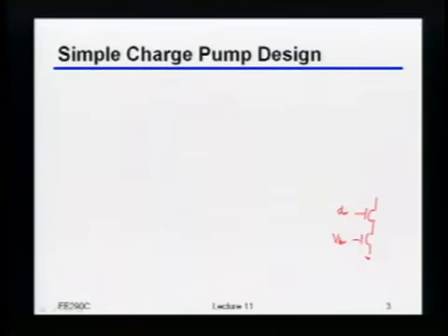We drew one version of the charge pump, which I'll sketch on the side over here. We had some current source device, and then some switch that was either connected to down or up, depending upon which direction you were going. I just want to quickly redraw a slightly different version that turns out to be slightly more common in most of the implementations that I've seen.